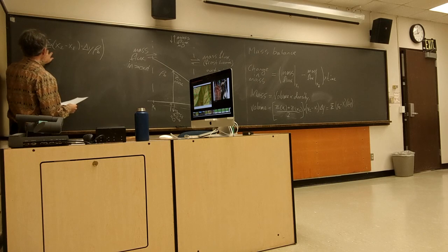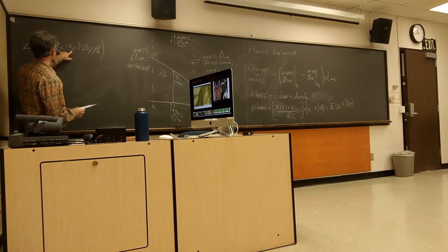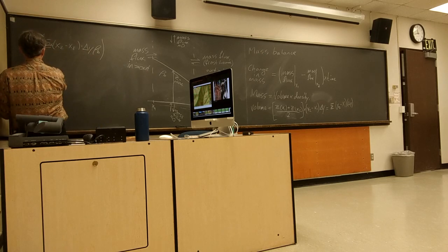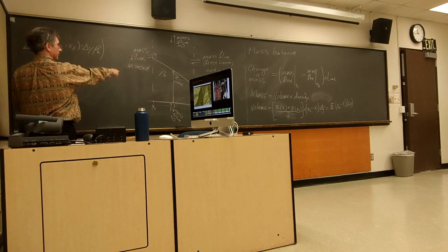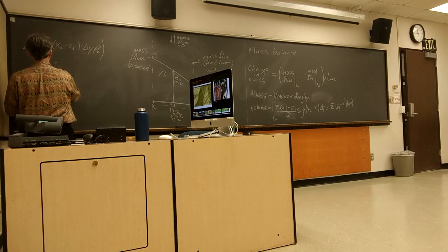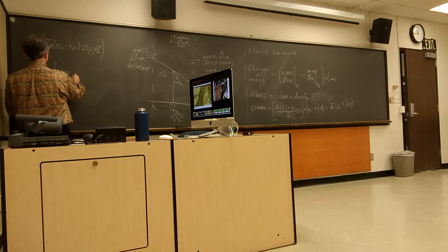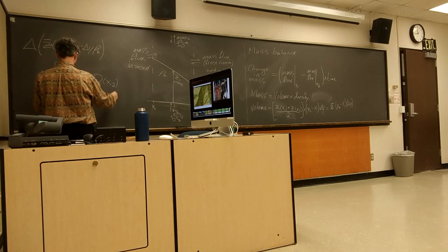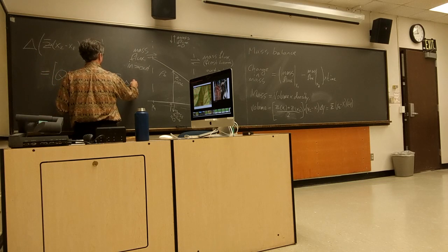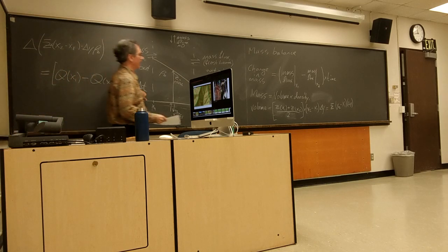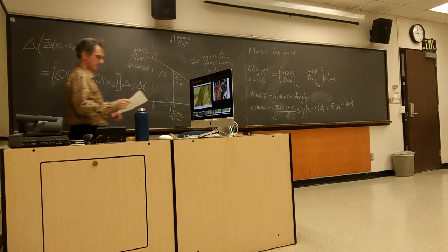So change in elevation times the distance increment times the lateral increment times bulk density is going to be equal to the flux at the side minus the flux at that side, times, all right, so here I'm using flux, big mass flux Q as a function of x, so Q at x1 minus Q at x2, times delta y and delta t, which is what I'm going to call my time increment there.